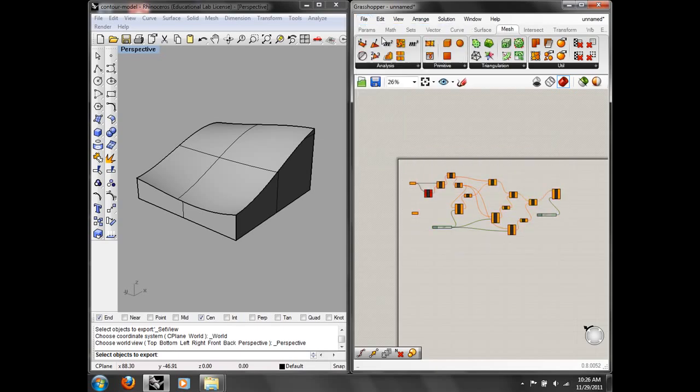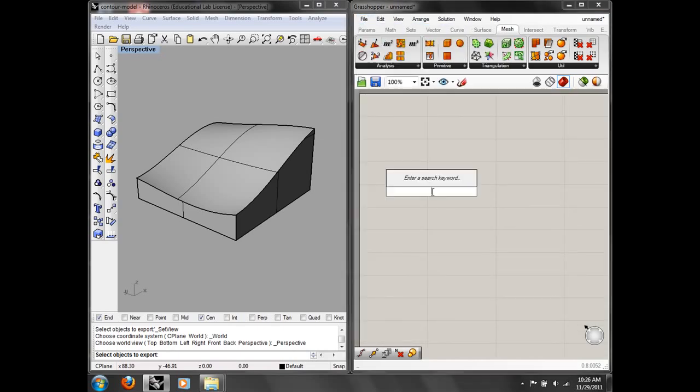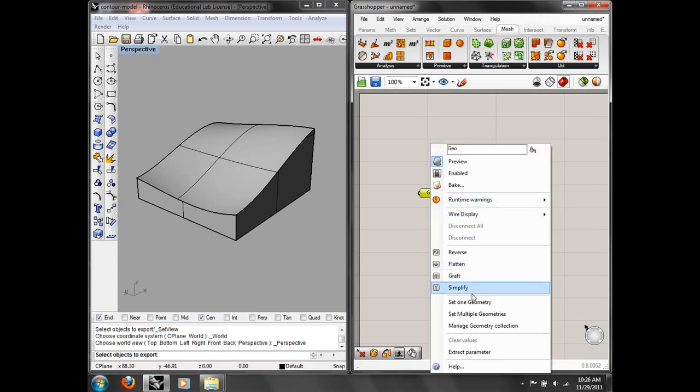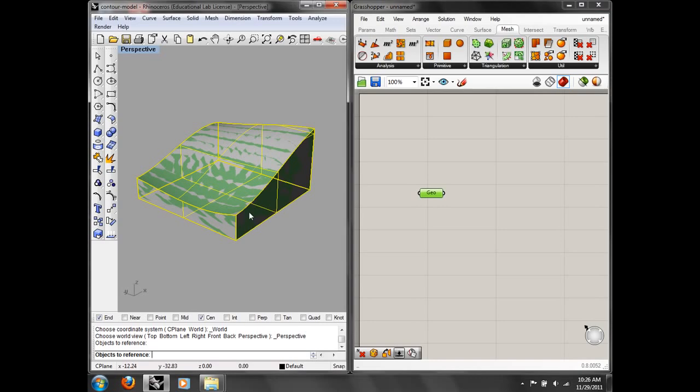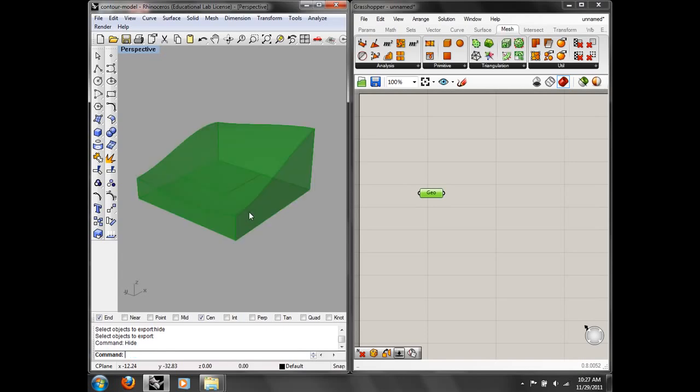Okay, so first things first, geometry. We got geometry. This is a solid model. What I'm going to do, I'll explain to you before I do it. I'm going to parametrically take sections of it. I showed you guys just earlier how I could take a section of a B-rep. There are lots of ways to do this. I'm going to make a bunch of planes and use those to cut sections. Then I'm going to take those sections and orient them to each other, and that's going to create my cut sheets.